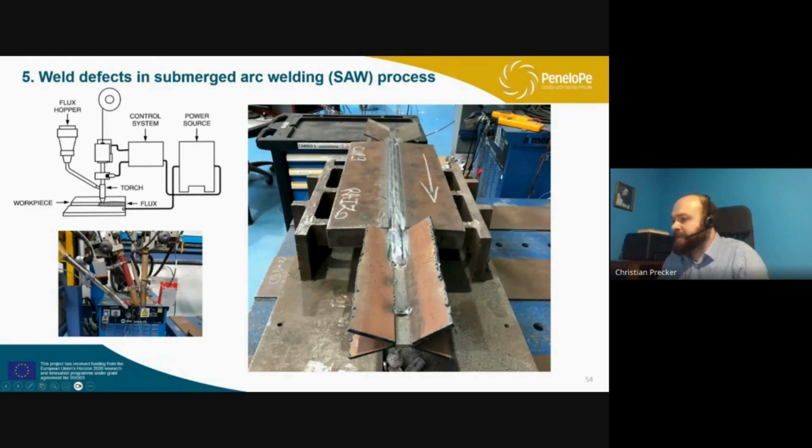And what you see here in this solid part are some crust, or let's say solid parts, that were over the weld from the flux. Because when you pass here, the flux that is in touch with the weld becomes hard and makes this kind of pieces here. And the excess of flux you can recover with the vacuum system. Okay, this is the general overview of this process, so you can understand.